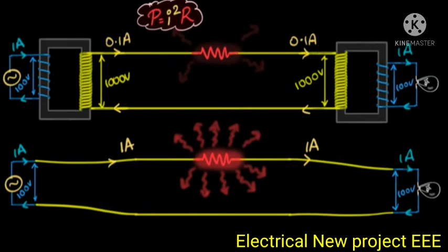Now at this point I had one more confusion. Yeah, I used to be a confused kid. See, people always say power loss or heat dissipated is I square R losses, but hey, power can also be written as V squared by R. And so if I look at this equation, with more voltage I would get more power loss. So doesn't that mean stepping up the voltage actually increases the power loss? What's going on over here? Can you pause the video one more time to see if you can explain this yourself?